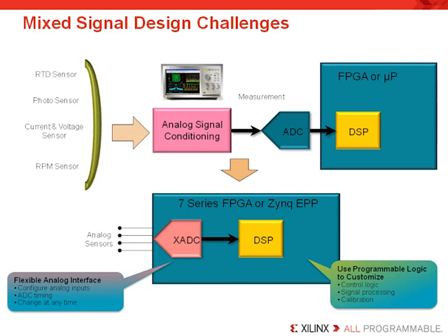Calibration using the FPGA can significantly reduce cost by eliminating components and reducing the PCB footprint of analog circuits. It can also provide a platform that is easily reprogrammed to address a range of sensors and application needs. However, the analog to digital converter, the ADC, is the key to enabling such an approach, and the Xilinx ADC core in the 7 series FPGAs provides unique flexibility and functionality beyond what is typically found in ADCs integrated into microcontroller units.